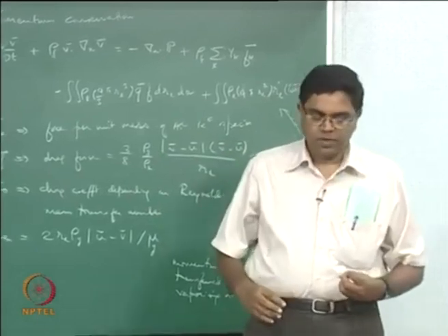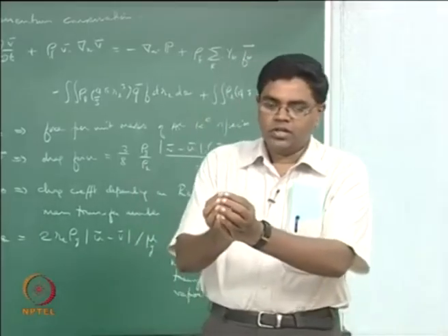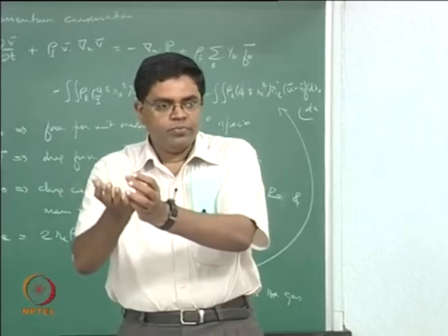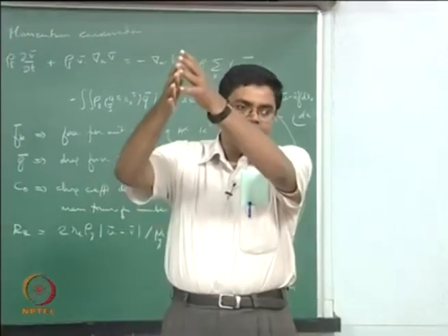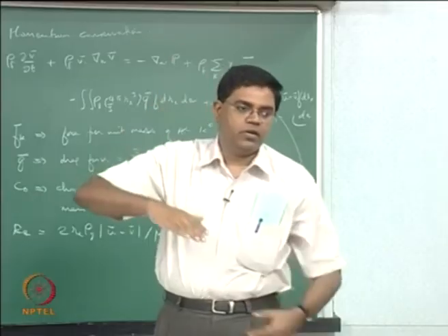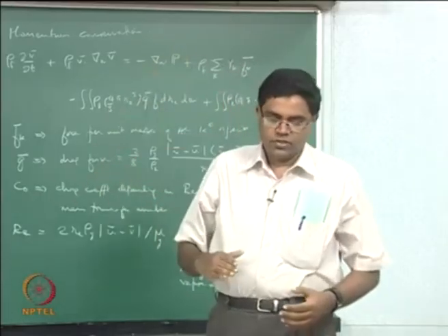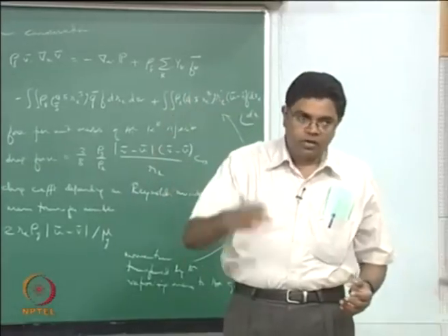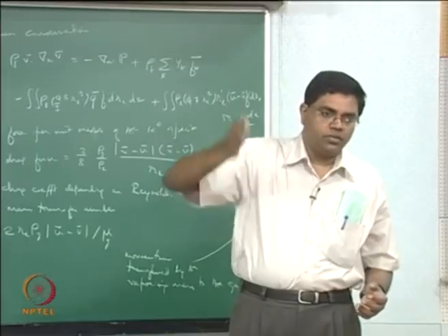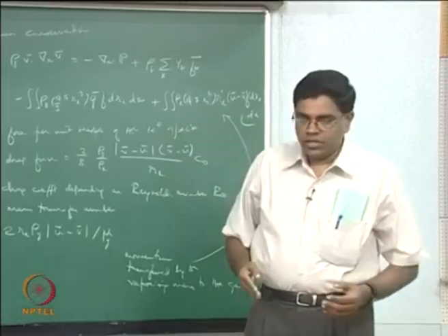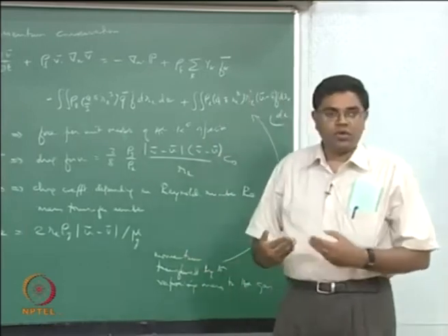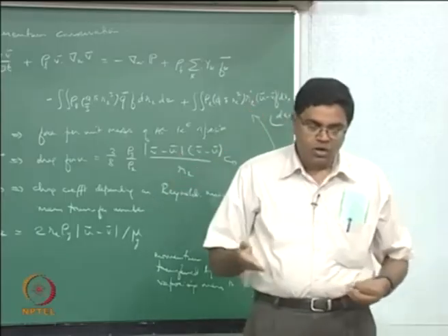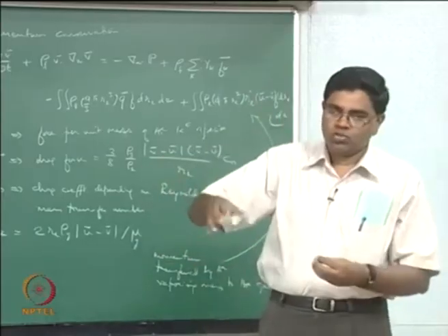So a simpler experiment for that would be, if you now have a droplet and let's say a gas flow coming from the bottom, you now have a flame that is getting elongated along the flow direction, right? You could still think about something like an envelope flame that is enveloping the droplet all around but getting elongated along the direction of the flow, right? But then as you increase the relative velocity between the droplet and the gas, you get into a situation where you no longer have an envelope flame, you now have what's called a wake flame.